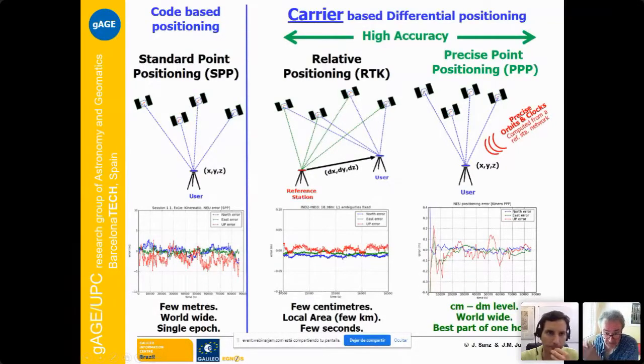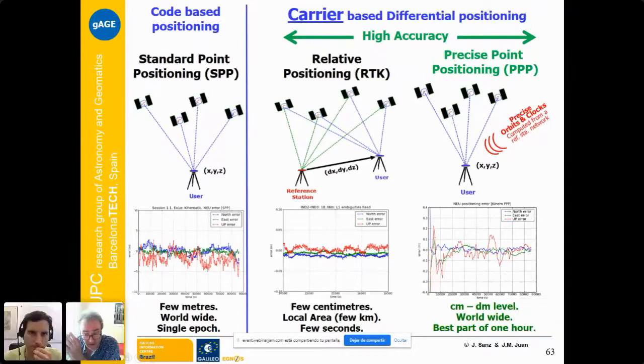To get in the vertical component 3 meters of error is good, is very good. In the vertical component, it depends on the number of satellites in view. This is single constellation, using only GPS satellites. I think that it was in Europe.